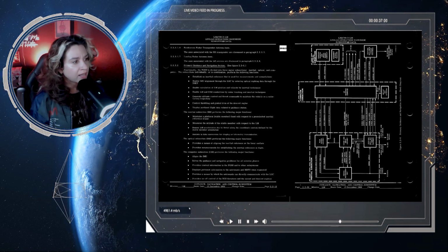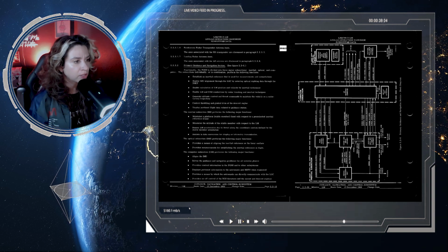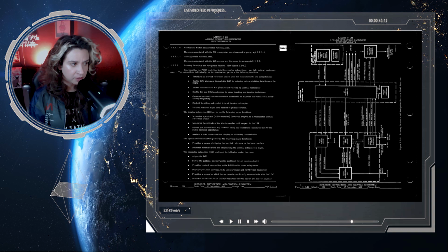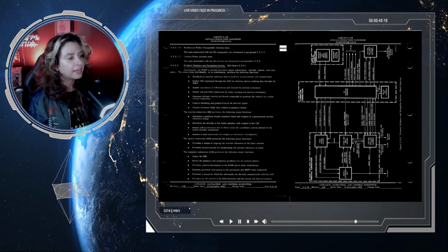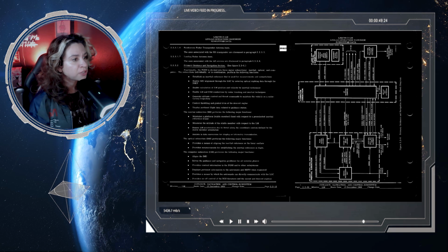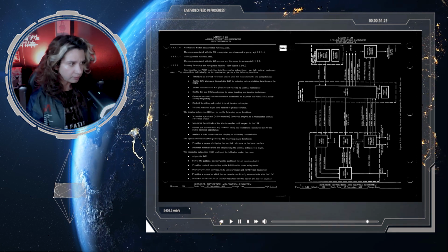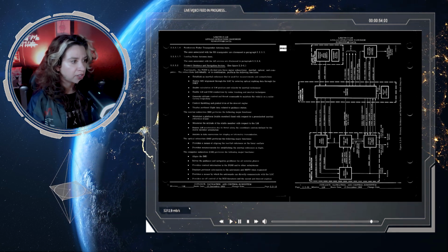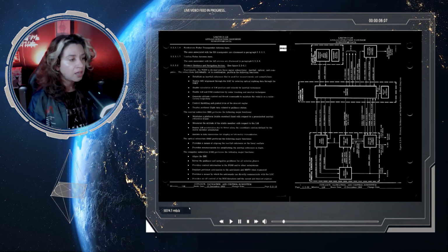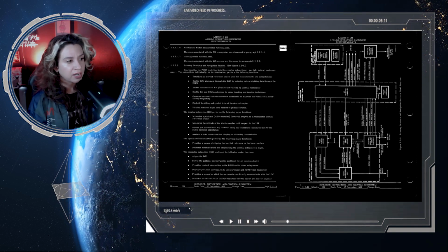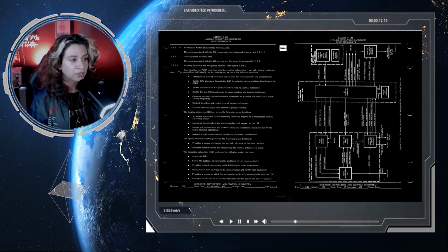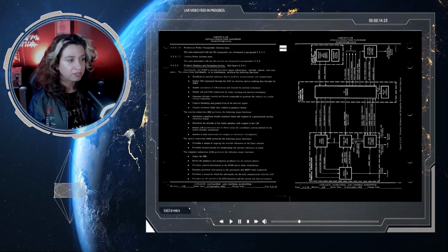It senses the LM acceleration due to the thrust along the coordinate system defined by the stable member orientation, and assists in the data conversion for display or telemetry transmission. The optical subsection, or the OSS, performs the following major functions. It provides a means of aligning the inertial reference on the lunar surface. It provides the measurements for establishing the inertial reference in flight.